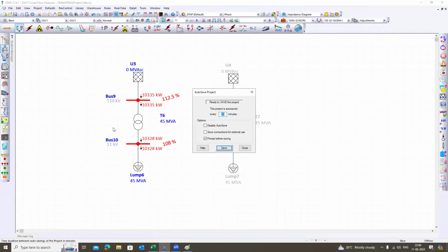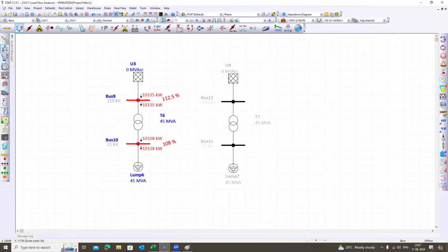Then how do we do that, sir? See, generally this reactive compensation will go for the solar and the RE sources especially. There, what you have to do is, with the different grid voltage conditions, check how much reactive power you are able to supply to the grid.